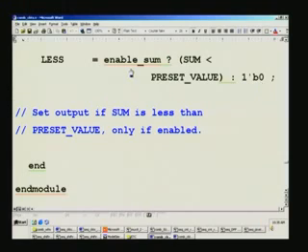The second input that we have seen here. So because it was made 0 here, 0 is appearing. If enable sum is low, promptly this 0 comes over to less, and so is the case for sum. So if you want a tri-state, remove this one, just put z there, right? So tri-state will appear there in case that's your need. If x, you can put x and so on. Any other data, of course, it should match. Being a 1-bit number, you have to give 1 bit, not higher bits. Otherwise, the compiler will complain.